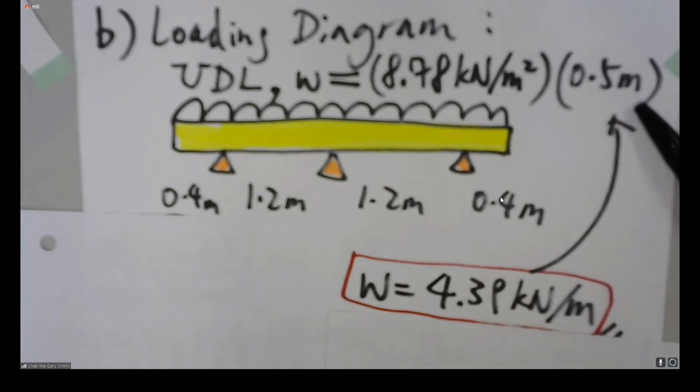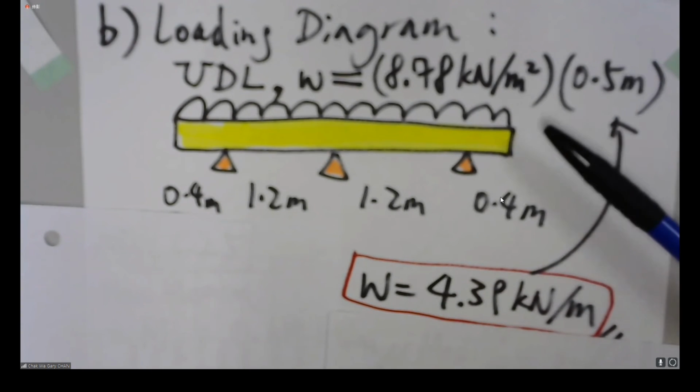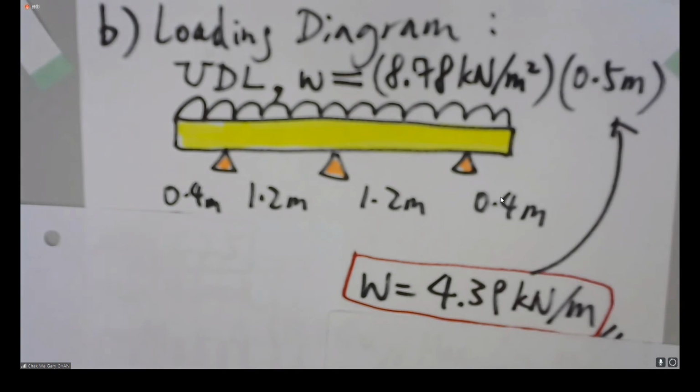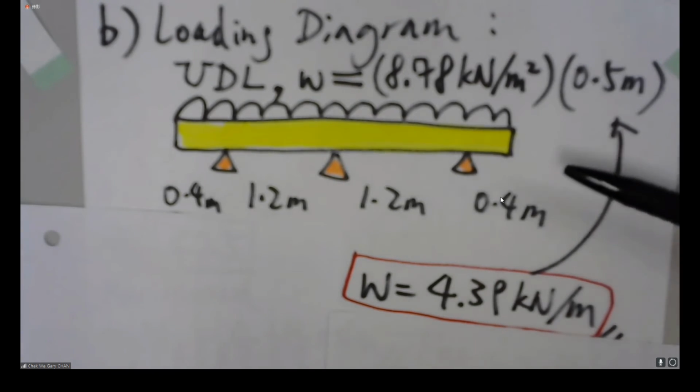Anyway, so are you okay with this one? How do we draw the loading diagram? So every time you should better draw the loading diagram before you find the maximum moment and maximum shear force. To calculate the maximum moment and maximum shear force, you have to look up a relevant load case.